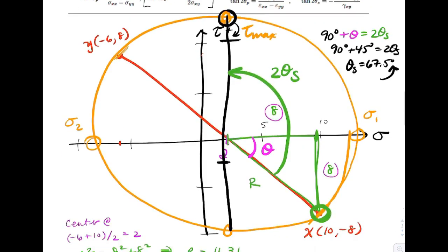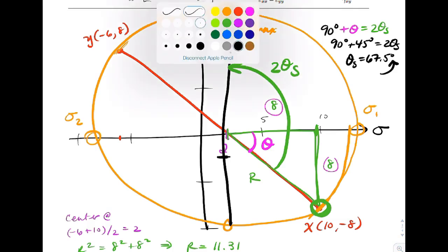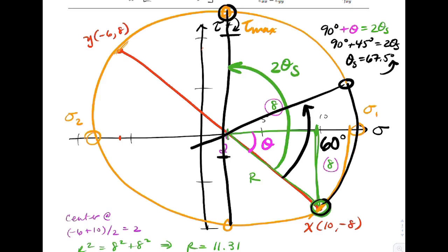The second part of the problem asked us to rotate this 30 degrees counterclockwise. On Mohr's circle, that rotation would take us 60 degrees. Angles on Mohr's circle are twice what they are in real life. So we want to take that x point and strike it through 60 degrees, putting it approximately right there. On the other face, our point is sitting right there. What we want are the coordinates of these points, which are the stresses on our face.